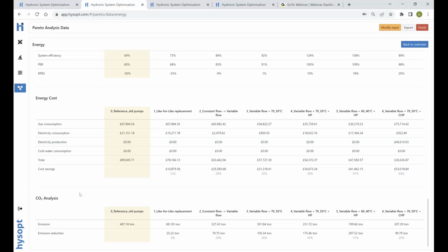Now, carbon emission factors are becoming more and more important. If you look at, for example, that 150 kilowatt air source heat pump, it already reduces 50% of that carbon footprint. Now we could, for example, run within the software a sensitivity analysis on different sizes of heat pumps to basically show where the most optimal heat pump size is compared to your KPI. So what's important is whatever your driver is or which ambitions you have, we are able to show you and make you a roadmap towards those ambitions.